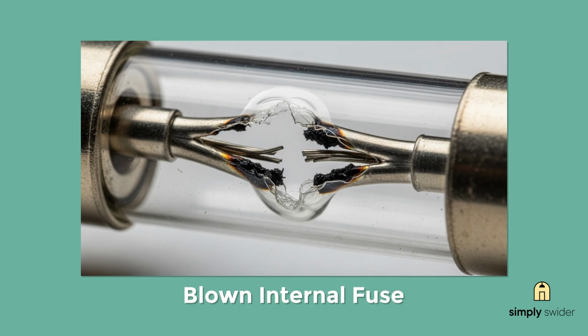Here's where things get a bit more involved. If your microwave has zero power, no lights, no display, nothing, you might have a blown fuse inside the unit. Power surges and outages can pop these fuses, and they're designed to protect the more expensive components.